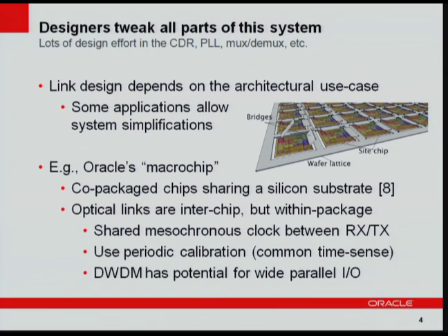Jack has mentioned this example slide of link-to-link connections between two chips in a microchip model. In each of these connections would be the transmit and receive system that was shown on the previous slide. What makes for some interesting design choices from a circuit perspective is that if you require some synchrony between these chips, for example during calibration, that might be possible if you share a slow clock among these, or some slow signals to indicate when to calibrate the receiver and transmitter.